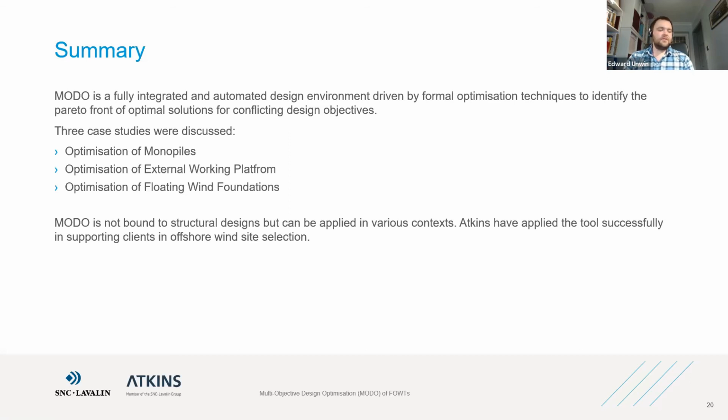The issue is you'd then be doing your turbine and spar mating operation offshore, which will require some quite high hook height, heavy lift vessels, and that's often quite an expensive process. So it's much more preferable from a cost point of view to try and do as much of that lifting and integration of the structure and the turbine as close to shore, or ideally alongside the quayside, as possible.